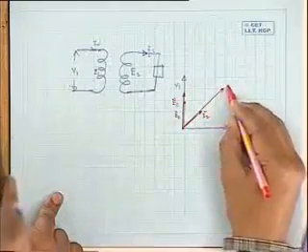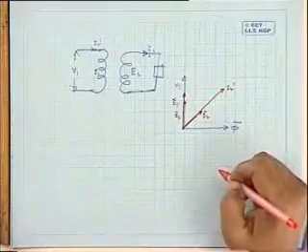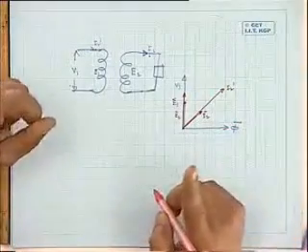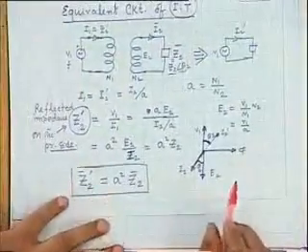What will be I2 dashed? You draw I2 dashed here only, along this line. Only thing, its length is changed because of the transformation ratio. But strictly in time domain, they are all in phase. Then why do people draw such a phasor diagram?